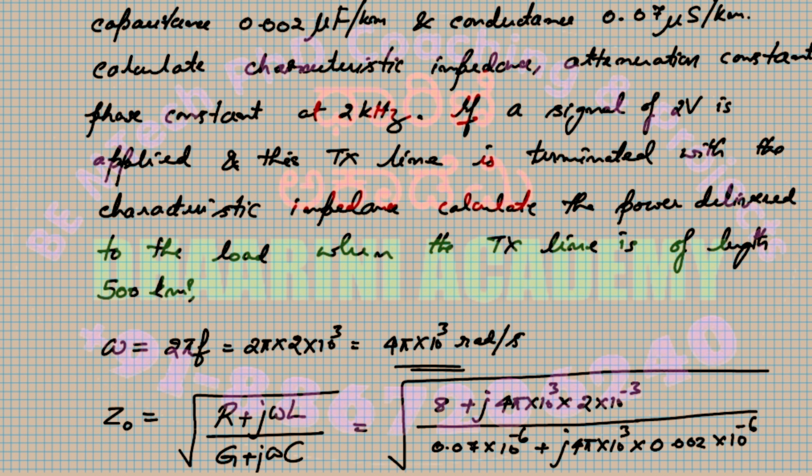So you see the power equation still remains the same. Power can be measured as I squared into R. P equal to I squared R is our fundamental equation. We are not going to change that. But which current you want to apply, you need to think, because there are many currents. I have a current that is being supplied, which is IS, or a current that is actually passing through the load, which is IL. Mostly we are going to use IL because we are looking at the power on the load side. So that gives you a hint that you should calculate IL somehow.